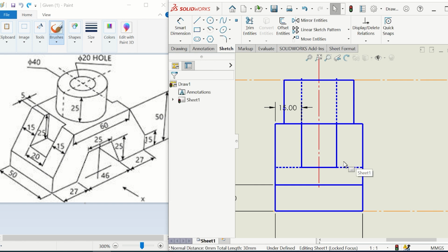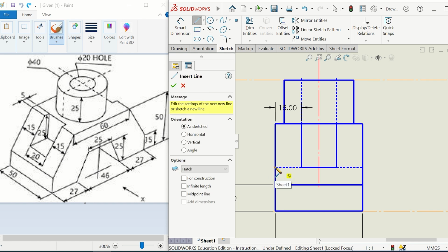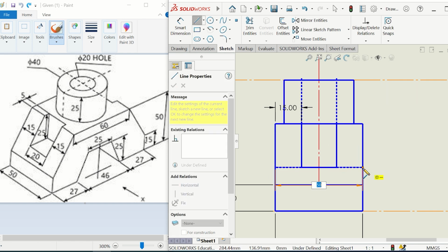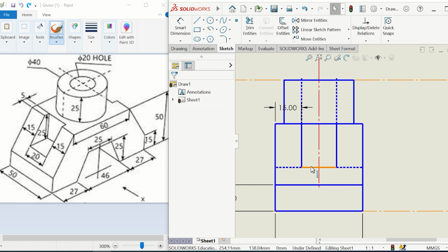Okay, from where do these lines appear? Why do they appear actually? In reality, this is one complete hidden line from here till here. However, as I was saying, it's overlapped here with a visible line, which is this. This is overlapping the hidden line, which is here. So I'm just going to represent it here as a dotted line. And from where do I get a hidden edge at this location? It's actually because of here.